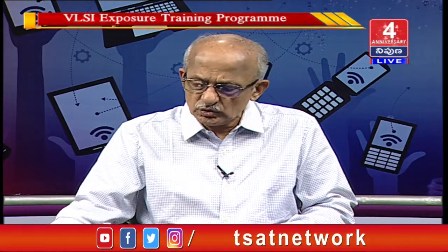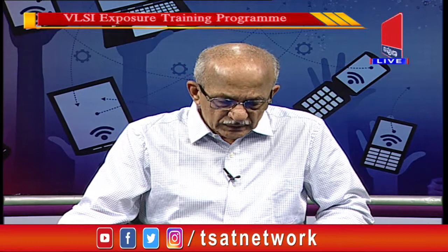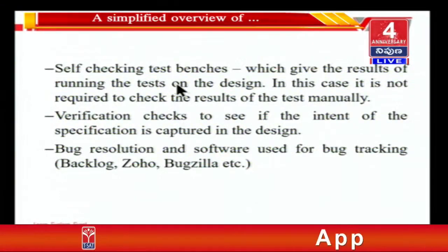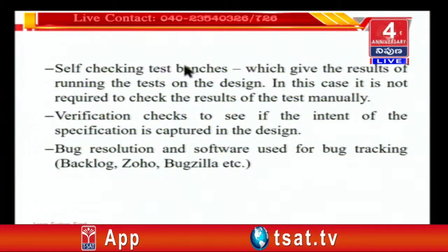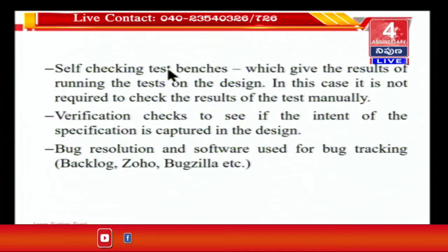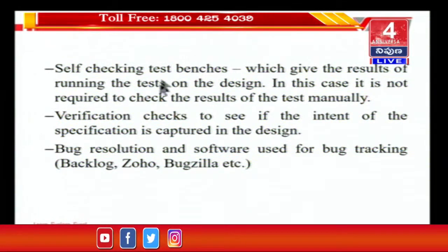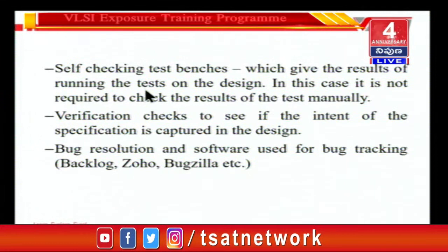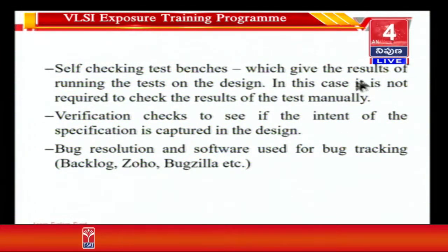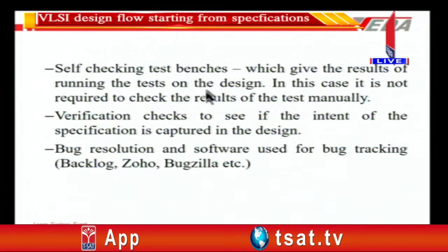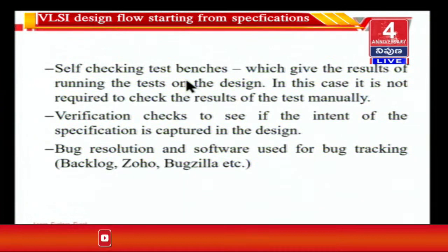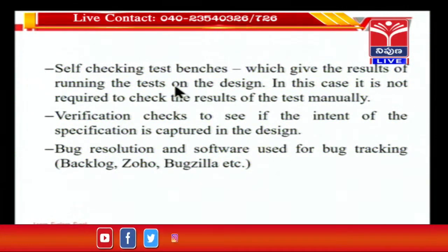The same thing that you do mentally can also be done in a program, and such logic incorporated into the test bench is what is known as a self-checking test bench, which gives the results of running the tests on the design. This itself gives the result. You don't need to sit there and analyze each and every waveform. That analysis you put in the test bench itself. In the case of a self-checking test bench, it is not required to check the results of the test manually. It will be done automatically by the test bench because you have provided that capability in the test bench.